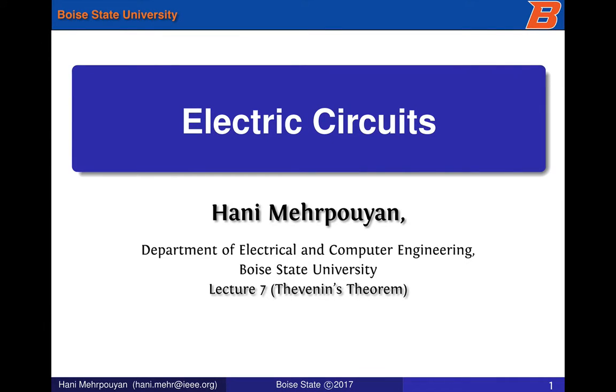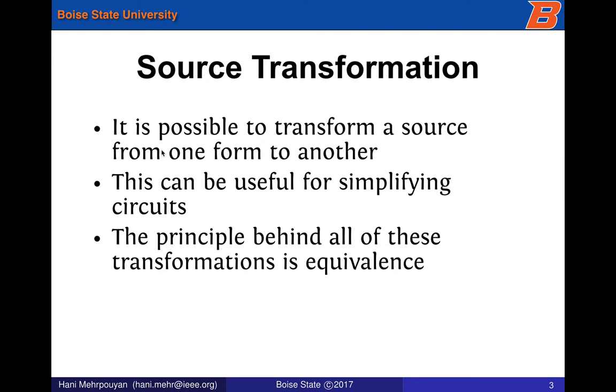Hi everyone, today we'll be discussing Thevenin equivalence and source transformation, and we'll get started with that. We've gone over the overview before, so I'll start with source transformation. When we're talking about source transformation, we're talking about voltage sources and current sources. If it's beneficial, we could convert a voltage source into a current source in a circuit, and vice versa.